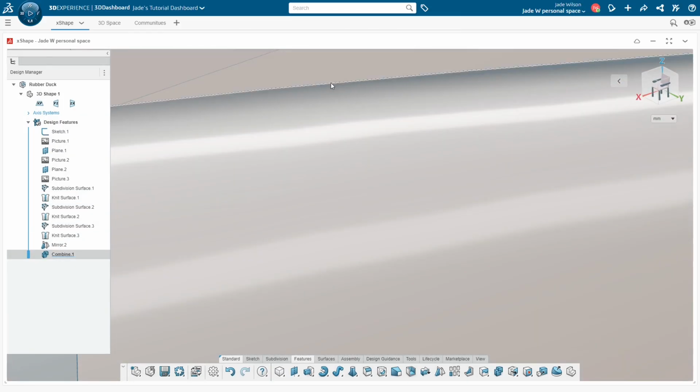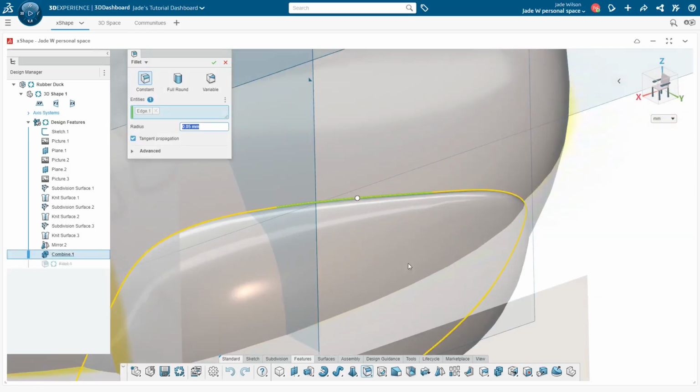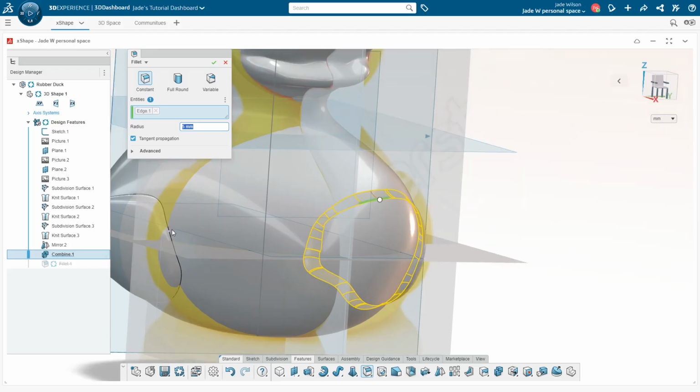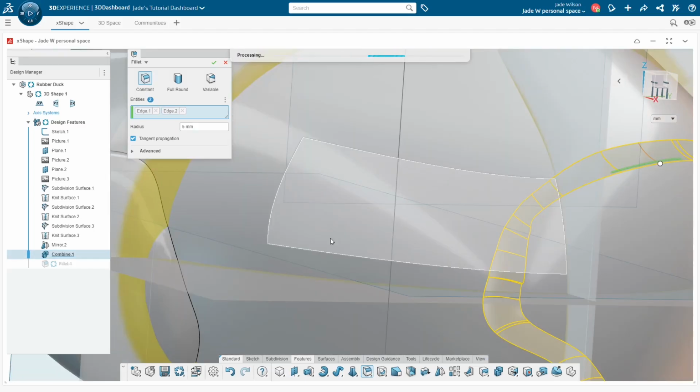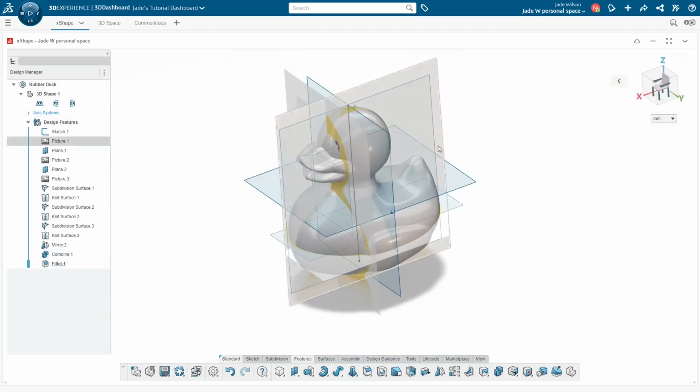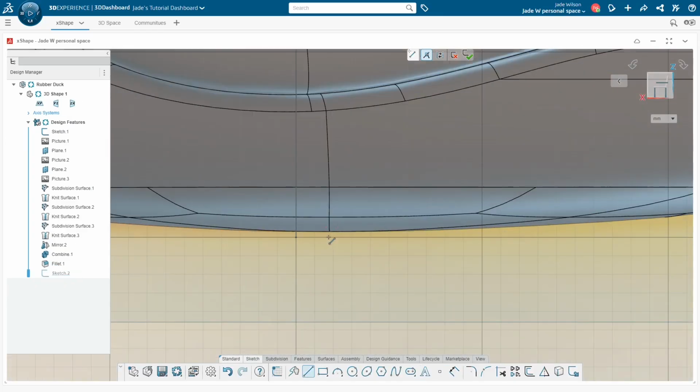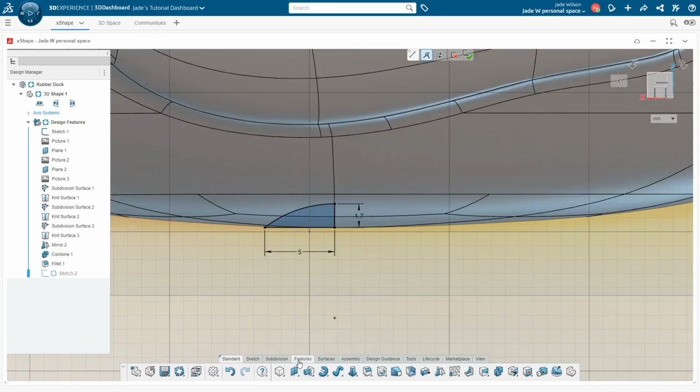This allows me to add a small 5mm fillet around the edge of the wing, creating a more moulded appearance to the rubber duck. The next feature of the duck is the squeaker hole. For this element, I revolve cut a dome out of the base.